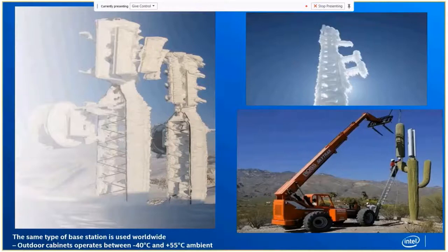Sometimes when you heat the chip up, the part just expands a little bit, right? You will see connectivity issues that are not seen at room temperature. We had horrible experiences in years past where the customer kept saying something is not working reliably, but test all you want, same traffic, same test equipment, everything works fantastically. And then finally people figured out the temperature was the issue. When you heat it, the board bends or the part bends and connectivity goes away.